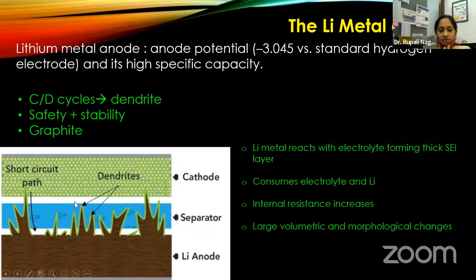Now, when you are constructing a cell, lithium metal which is in contact with the electrolyte starts forming what is known as SEI, the solid electrolyte interface.